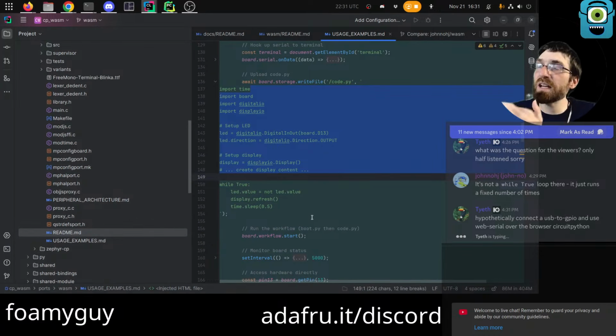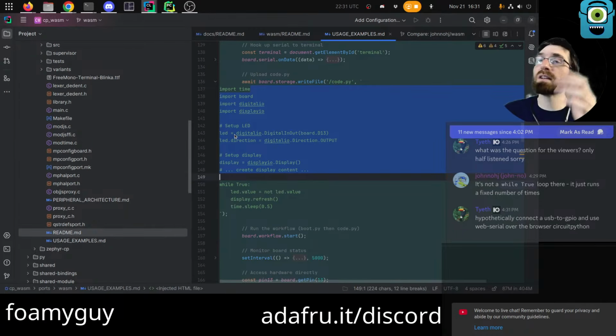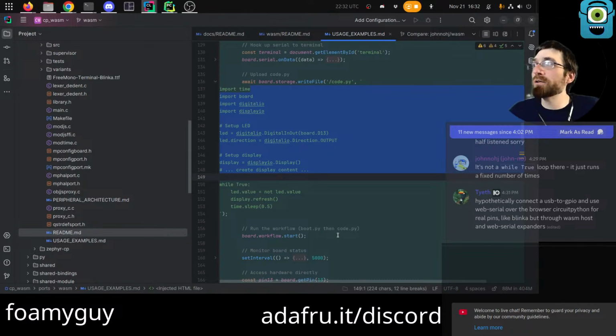And that could be like a test case for libraries. So if we had an I2C library or whatever, it could do a scan and find itself as long as everything is working. Or if we had the debouncer library, it could verify that the debouncer library is actually behaving how it's supposed to against this port inside the actions, which is super cool, because right now we have no way to test on any CircuitPython thing in the actions.